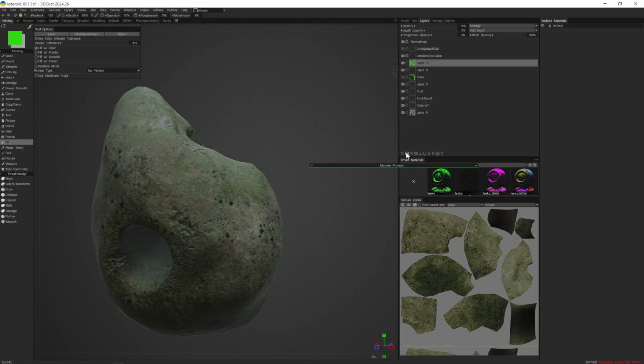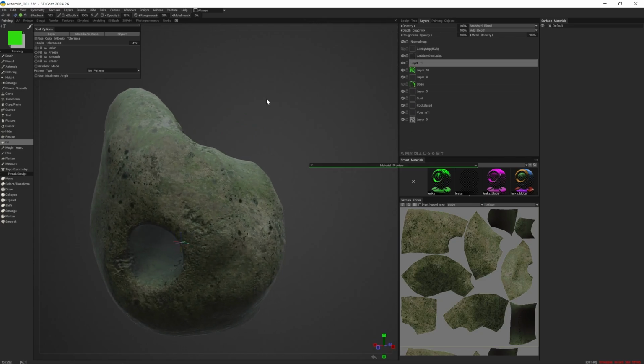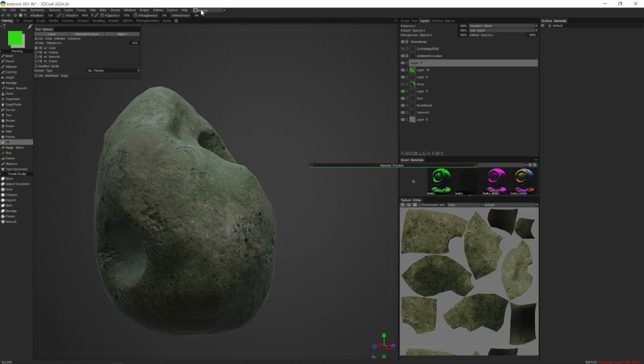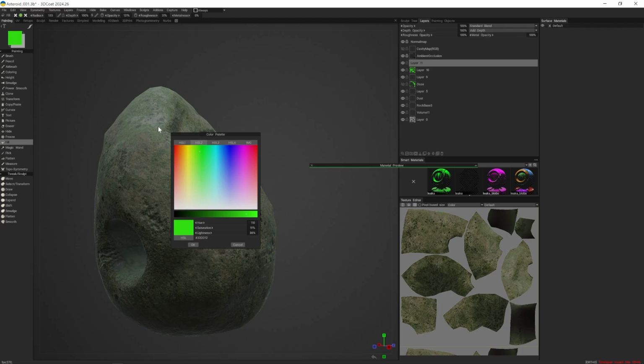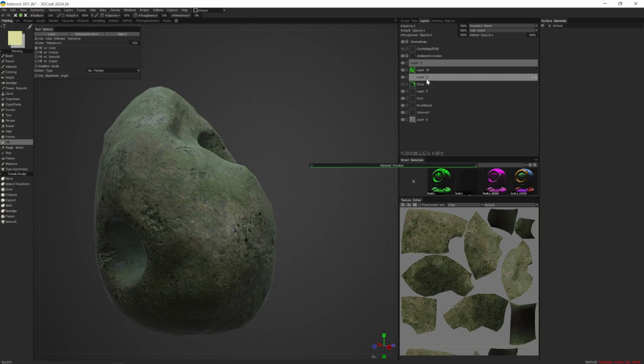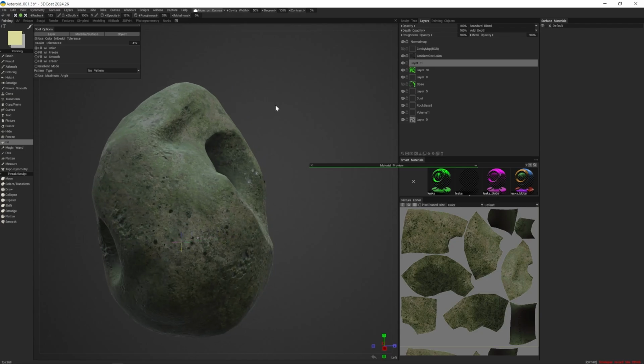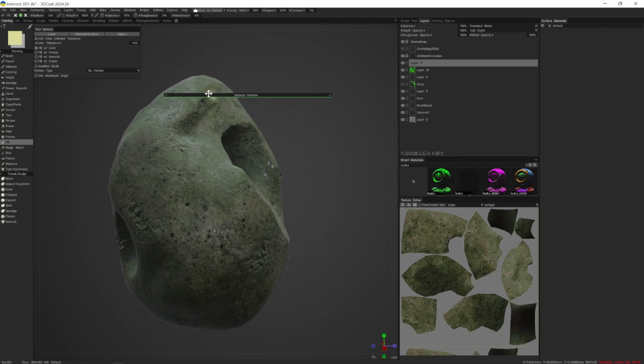There's a couple other things that we can be aware of. So I can go in here up top. You'll see it says always, and we still have these. So I can turn some of these off. So let's turn off both the depth and the glossiness and just leave color. And I'll change my color to something maybe like that. And I'll make another new layer here. And instead of setting this paint mode to always, I can set this to something like more on convex. Okay, when I set that to more on convex, I can preview this.